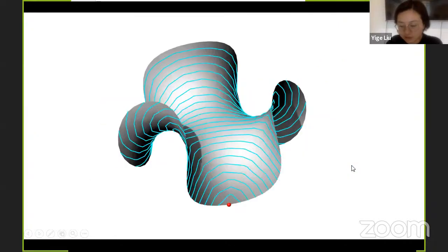So this gives us a clue how to generate a knitting pattern over 3D geometry. We first generate evenly spaced parallel lines as warps onto a 3D surface. Here I give a reference point, so all the lines are arranged in this direction. You can also give this point at other places on the geometry.